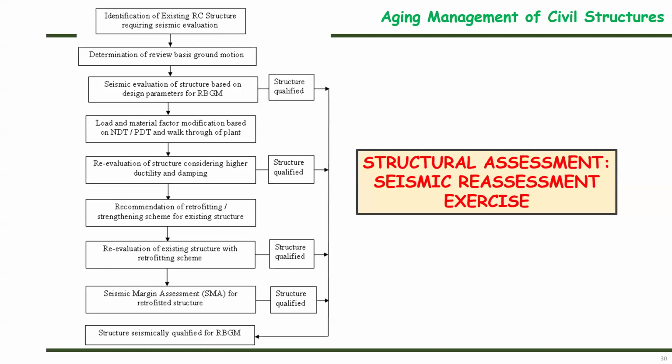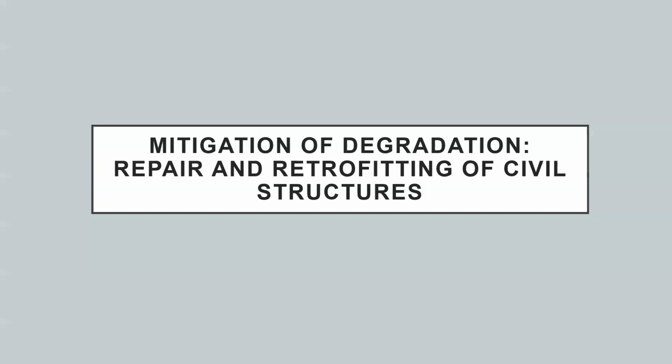Okay, so now, after designing the retrofitting scheme, we can even check how much seismic margin is available with respect to the seismic demand. For this, we usually carry out nonlinear static pushover analysis. So this is the entire flow chart for carrying out the structural assessment, that is, the seismic reassessment exercise.